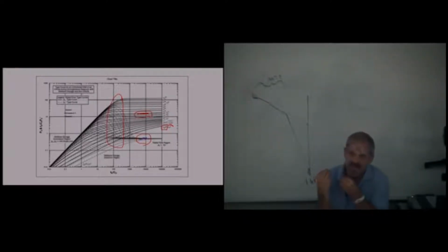Because I'm able to make this plot, I'm actually able to change time and pressures into dimensionless time and dimensionless pressure, knowing perm and skin, and placing my data on this plot. Actually, knowing perm fixes my y-axis. I still don't know level or storage, so my x-axis is still variable. I can move that a little bit to the right or left because my lines are horizontal. I can't move it too far to the left because I move out of the middle time region.